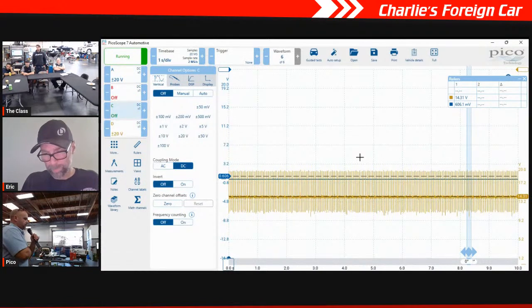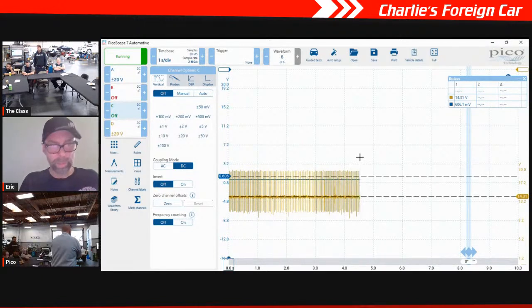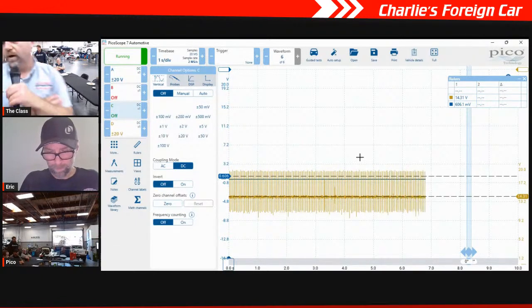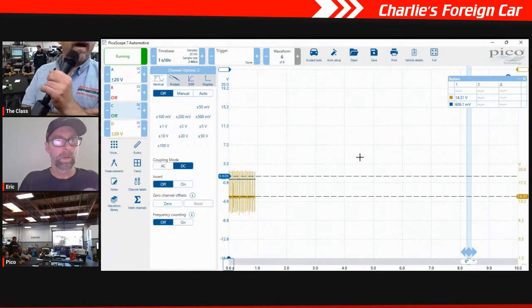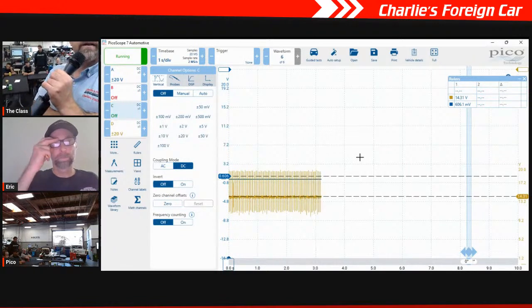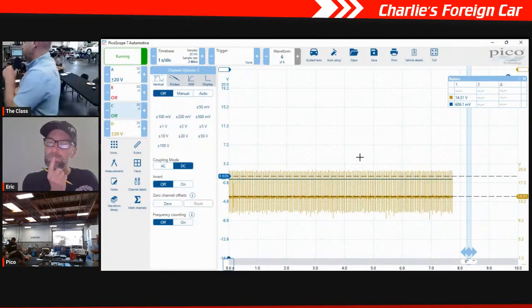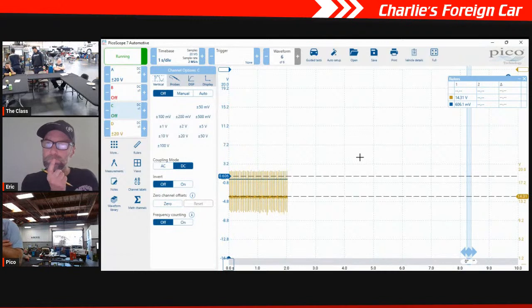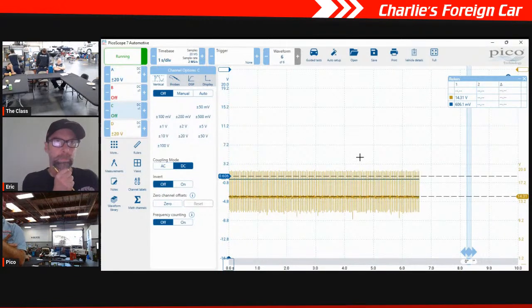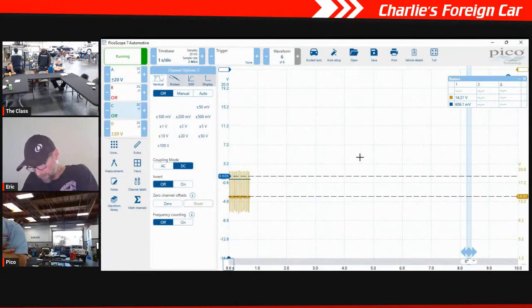Okay, so weren't we looking at the angle last time? We were, but there's no angle. It doesn't show the same figure on the exhaust as on the inlet. Yeah, it's different. It's showing outlet camshaft adaptation, outlet camshaft shifting angle, which it doesn't show on the other, and then camshaft shifting angle nominal value.